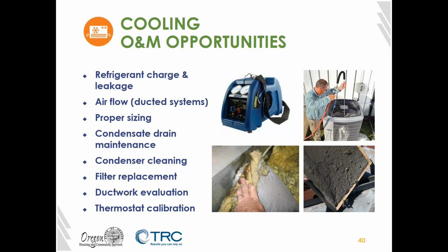But that being said, you might have a building where the top and bottom are super tight and you have giant leaks in your walls, and so for you it might make the most sense to test or to do air sealing activities in the walls. So I think it helps to start with a prescriptive list of like, are all of our doors air sealed? Are they well gasketed?